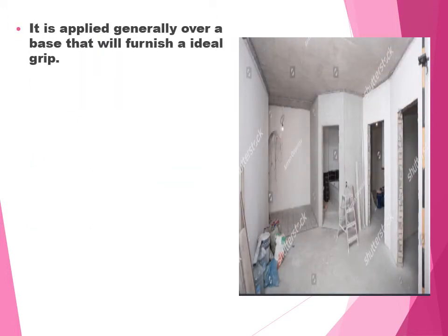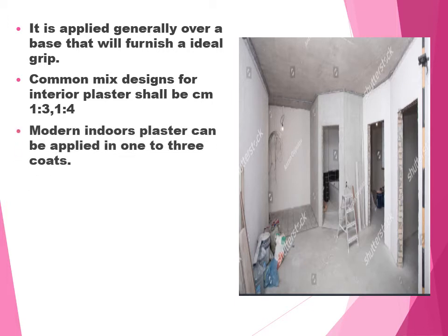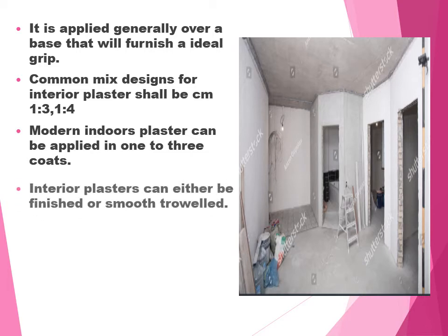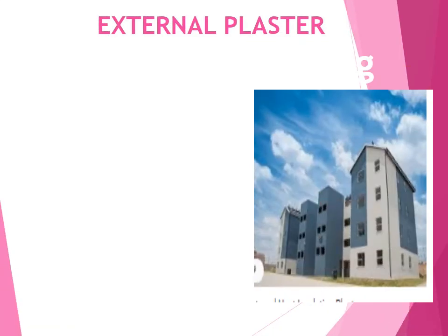It is applied generally over a base that will furnish an ideal grip. Common mix designs for interior plaster are cement mortar 1:3 and 1:4. Modern interior plaster can be applied in 1 to 3 coats. Interior plaster can be either a rough finish or a smooth trowel finish.